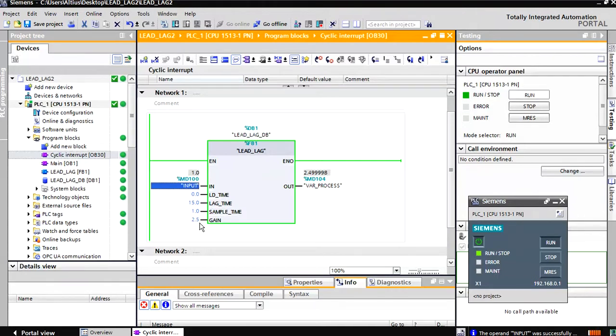And if you remember in the equations of the transfer function, the transfer function depends proportionally on the gain. The gain was the factor K. K was 1.0, but this time it's 2.5, and that means that the output will tend to 2.5. At this moment it is 2.499998, that is practically equal to 2.5. Okay, I return again as before to 1.0.